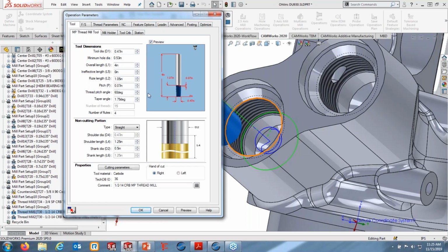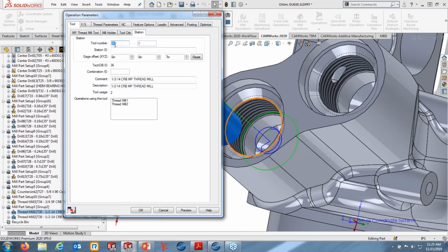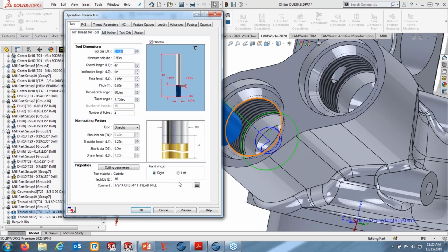The other enhancements that I mentioned also included better definition of the tool and things like that. So you had always your tool comment and all of your values here, but what about things like tool vendor, or some machines require a tool ID instead of a tool number. You're calling it using a script rather than a tool station number, for example. You're not using T1 or T2. You're actually using a verbiage or a set of phrases to call a tool change. In here, we've now got this option down here for additional details.